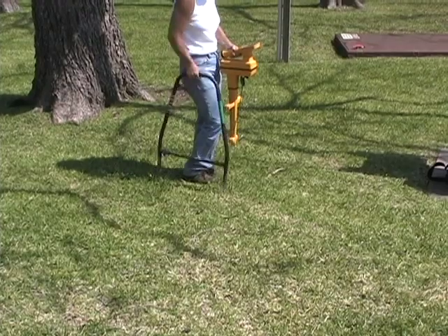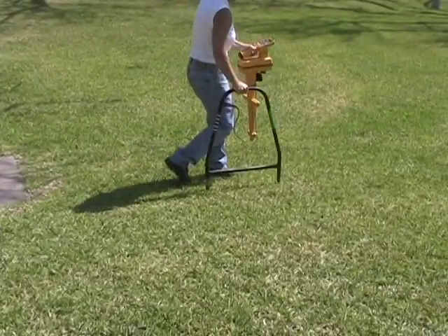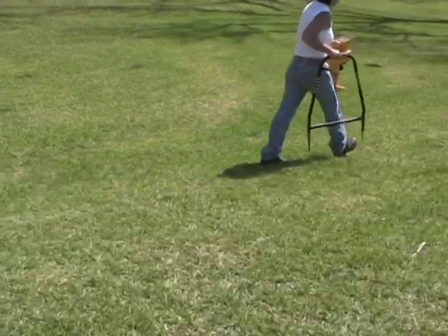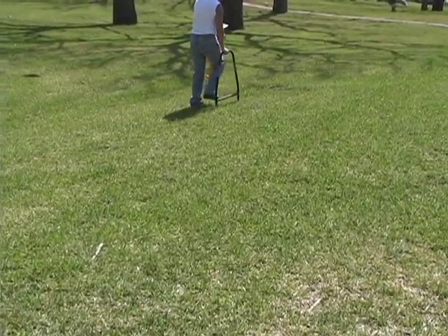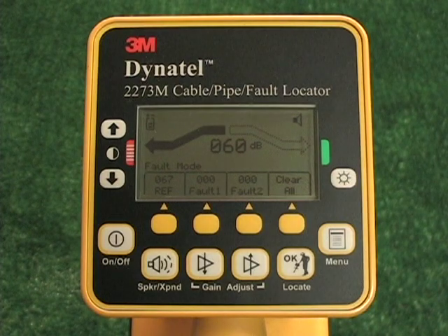Continue fault locating, reinserting the A-frame probes while watching the receiver bar graphs. The bar graph on the receiver will fill toward the green band on the right side of the screen, indicating that the fault is ahead of you in the direction of the green banded leg of the A-frame. When the bar graph fills toward the red band on the left side of the screen, the fault has been passed and is now behind you.